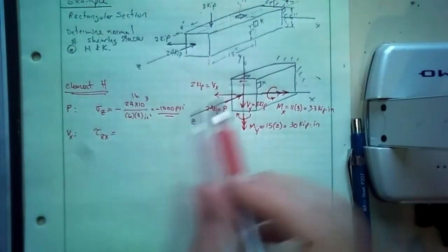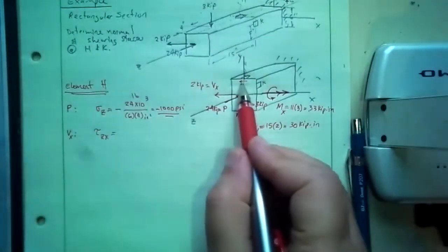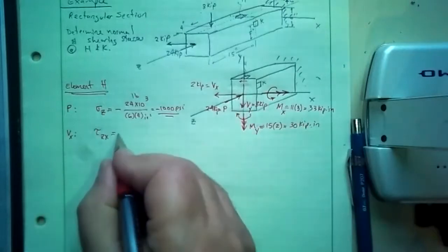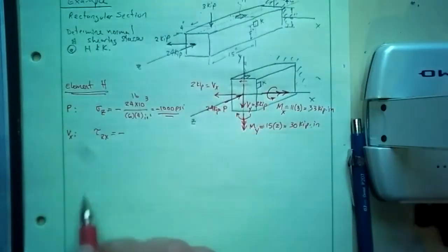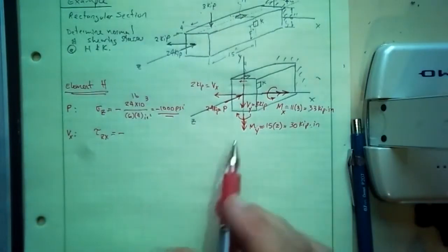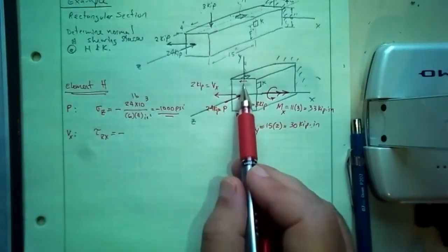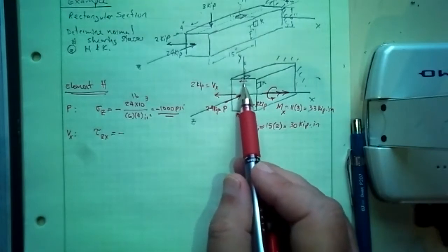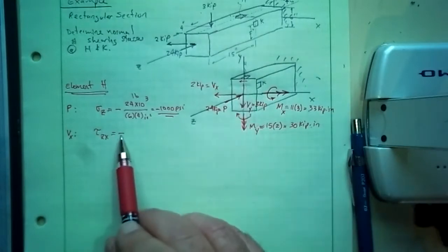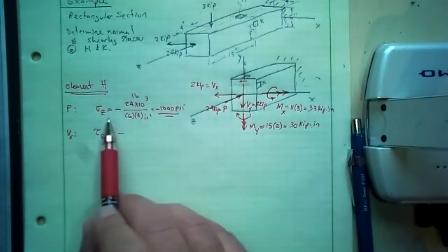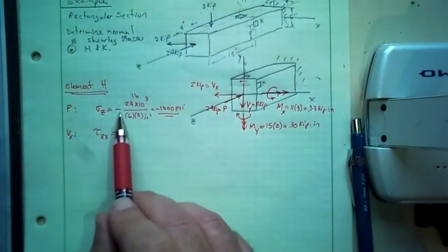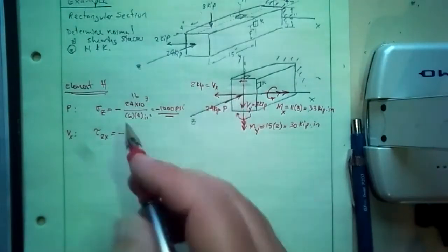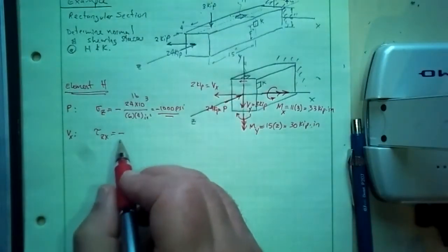Okay. So shear stress does not have a sign. But again, we can assign a sign based on direction. If it's pointing in a negative x, I'm just going to put a negative. So when I add or subtract, I will find out which direction is the dominant one, and I will take the sign off at the end. This just simply defines a direction. It's not like normal stress, where negative means compression. Here, it just simply means that's the direction. All right, so we're going to deal with that.